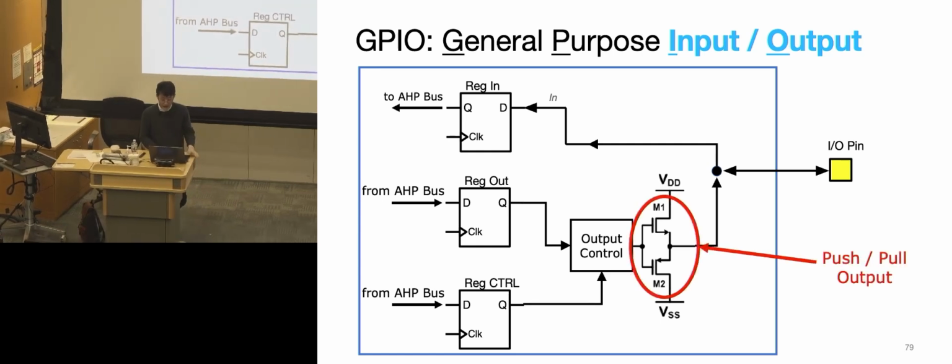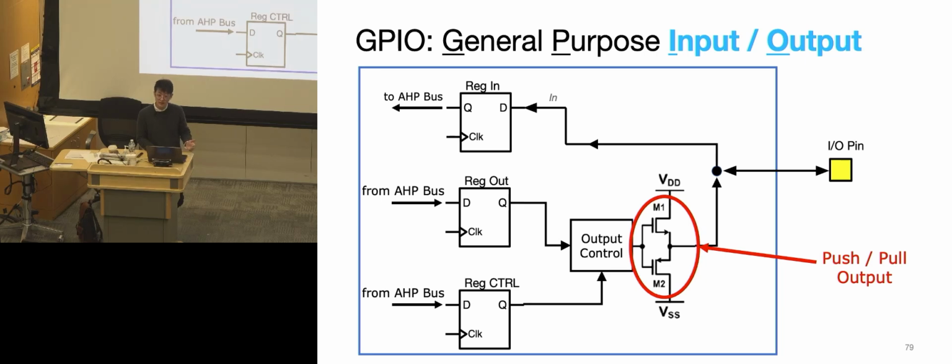And this is a push-pull pair, basically. You can think of it like a fancier version of a switch, like a couple of transistors put together. The advantage of this compared to a normal switch is you can use a small amount of current to drive a much bigger amount of current in the system. So it allows more current to pass. In our case, I think it's about 10 to 20 milliamps tops for the systems we will be working with.